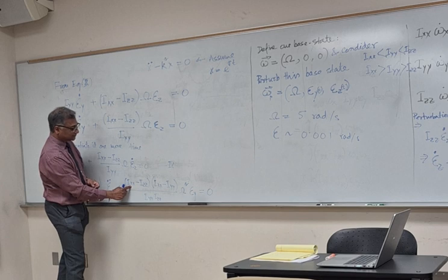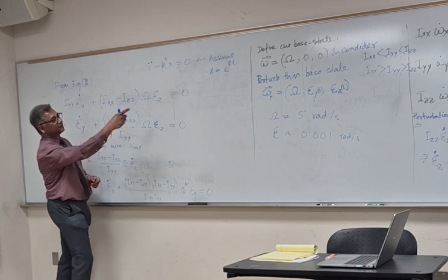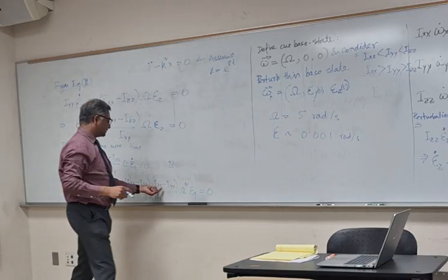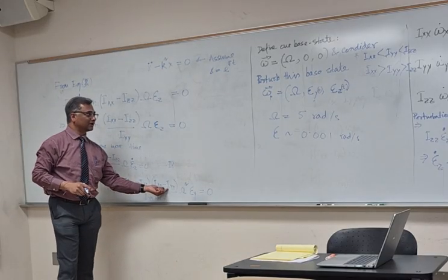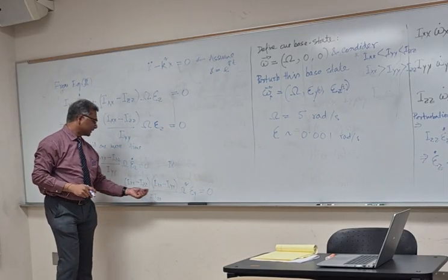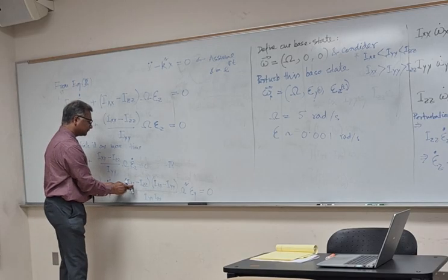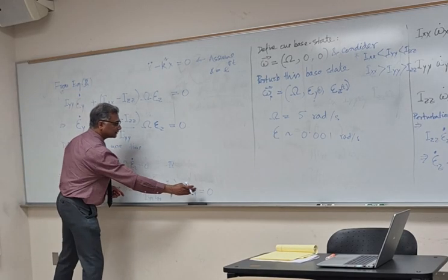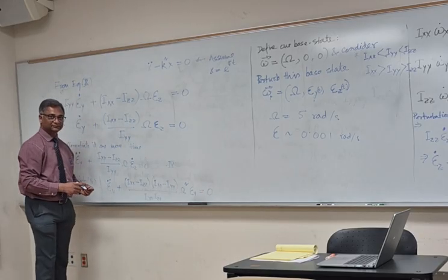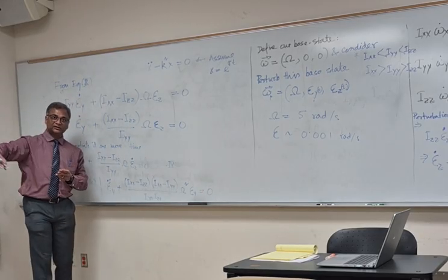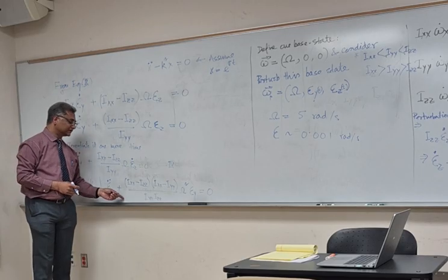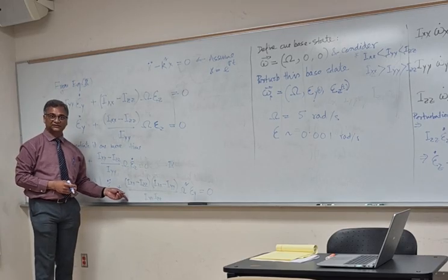Ixx is smaller. Consider the first one. It's negative. What about this one, Ixx minus Iyy? Also negative. So the negative over negative is positive, a positive numerator. So when we bring it to the right-hand side, it becomes negative. So it's e to the power of a negative t thing, right? So this is a stable state.